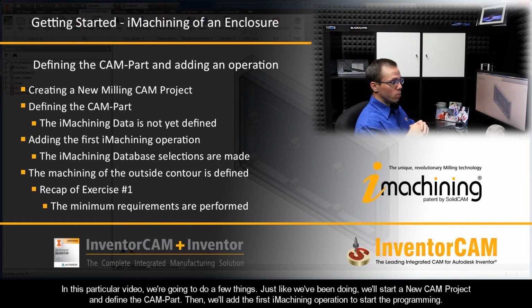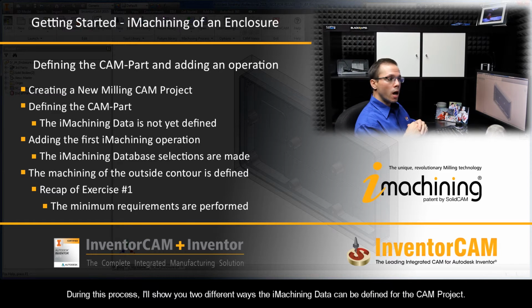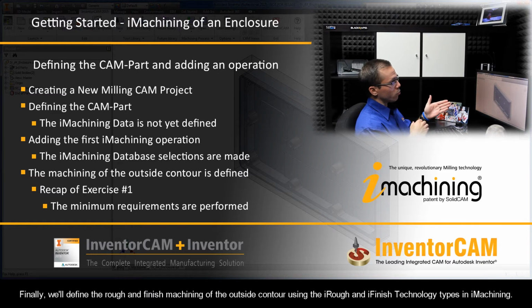Just like we've been doing, we'll start a new CAM project and define the CAMPart. Then we'll add the first iMachining operation to start the programming. During this process, I'll show you two different ways the iMachining data can be defined for the CAM project. And finally, we'll define the rough and finish machining of the outside contour using the iRough and iFinish technology types in iMachining.